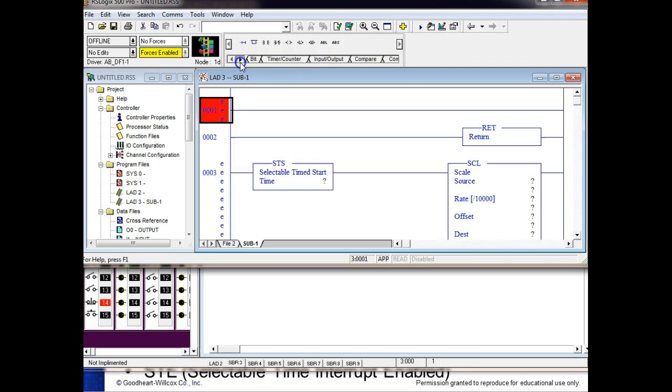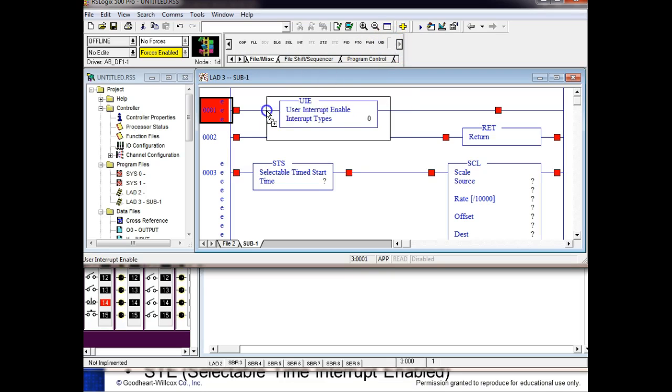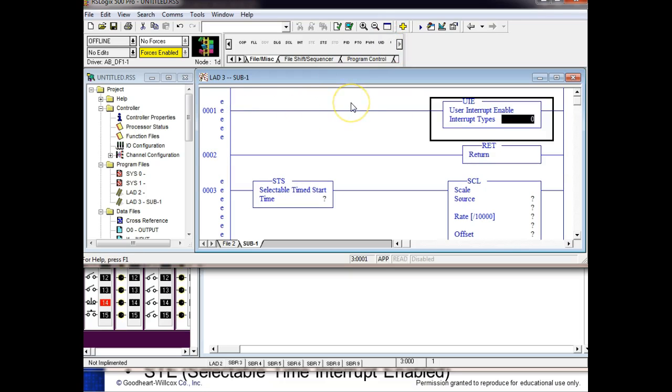And then we have what we call a maskable interrupt, which means you can turn them on and turn them off. That's probably what they give us available for right here. Keep going back, guys. So this little dash is an interrupt enable, so it's considered to be an output instruction.